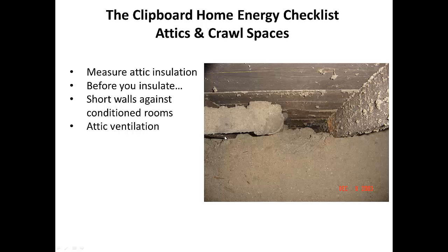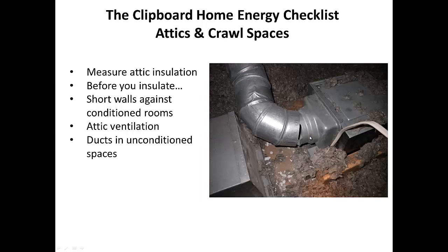And you have soffit vents, which are down low in the attic, that you can see when you're on the ground looking up from the outside. And then you have upper vents, so that in the summertime all the hot air in the attic can have a way to move out. But what we see here is that over time, or maybe with a bad installer, the insulation is covering up the soffit vent that's at the bottom of this insulation here.